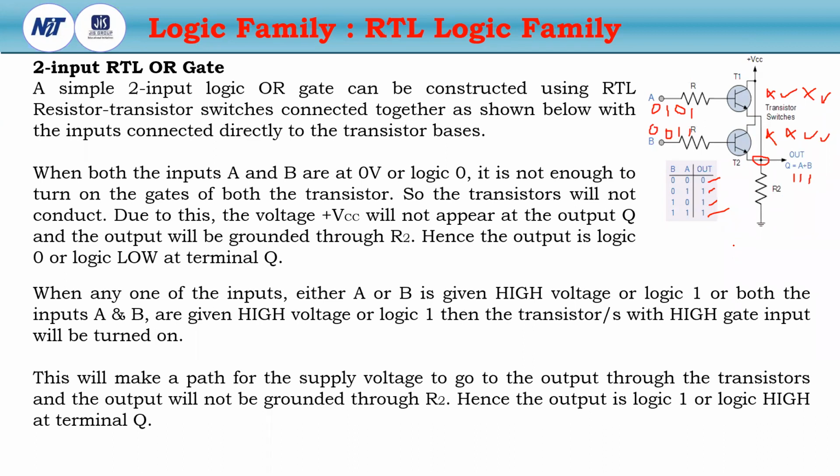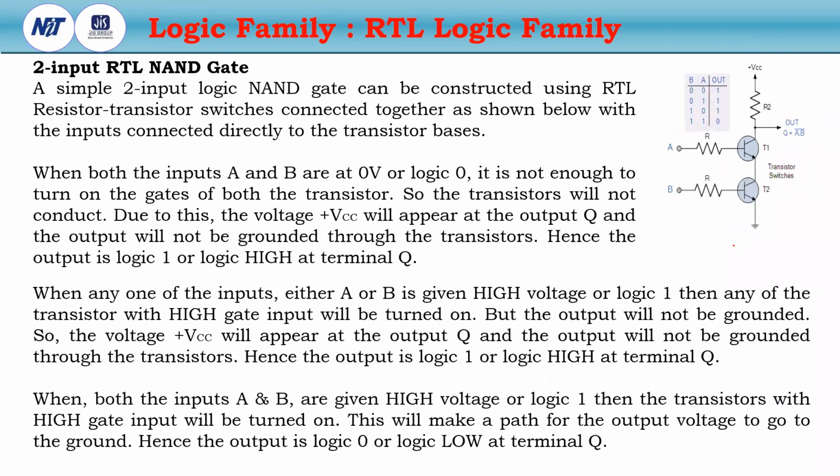The examples given are the NOT gate, AND gate, and the OR gate. Now come to the NAND gate. The driving resistors are connected with VCC. Before, for the OR gate, AND gate, and the NOT gate, the transistors are grounded; the resistance R2 is grounded. But here for the NAND operation, the driver resistance is connected with VCC. This is the simple difference.